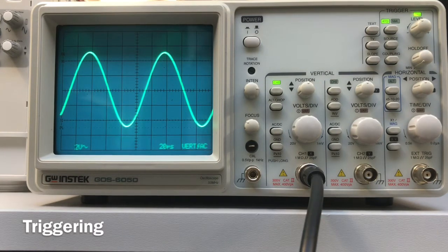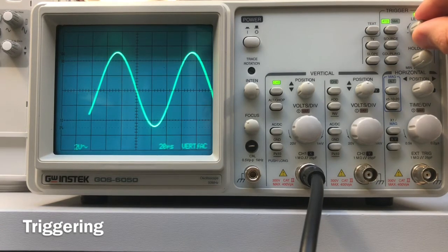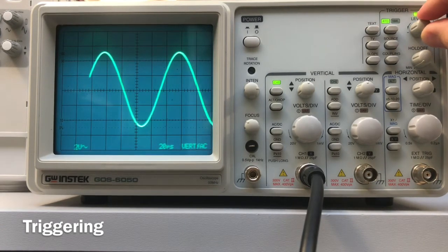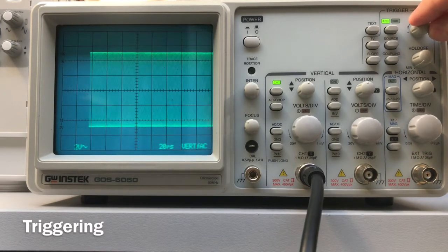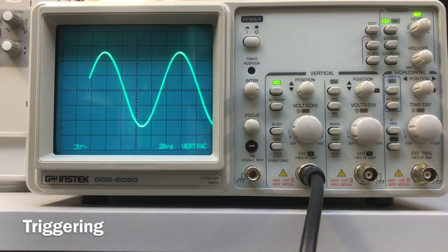Also, the oscilloscope has a threshold below which it does not display a signal. Basically, the threshold can be moved with the level scroll button here. So here's also the threshold where it is not triggered, and like that. It also has the hold off scroll button, which can be very useful to hold the flyback time for longer. This is more useful for more complicated signals. The flyback time is basically the time the beam takes to travel from the end to the beginning of the screen.